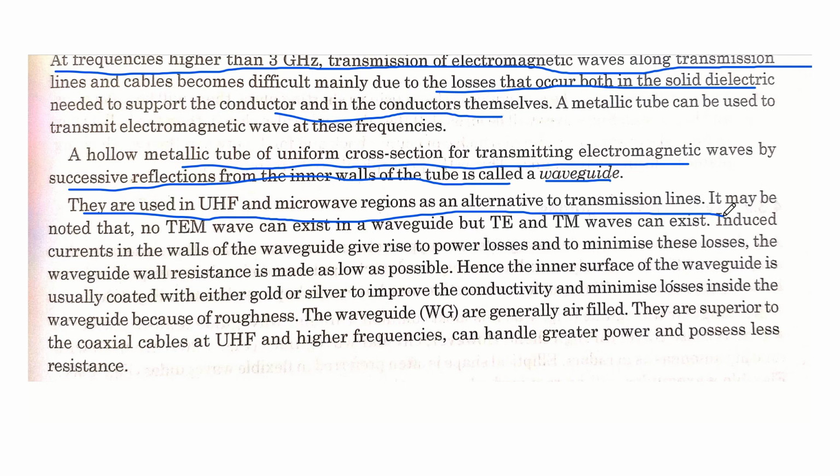I already told you these waveguides are used for transmission of ultra high frequency waves and microwaves as an alternative to transmission lines, meaning instead of transmission lines, here we are using waveguides for ultra high frequencies and microwaves. It may be noted that no TEM wave can exist in a waveguide, but TE and TM waves can exist.